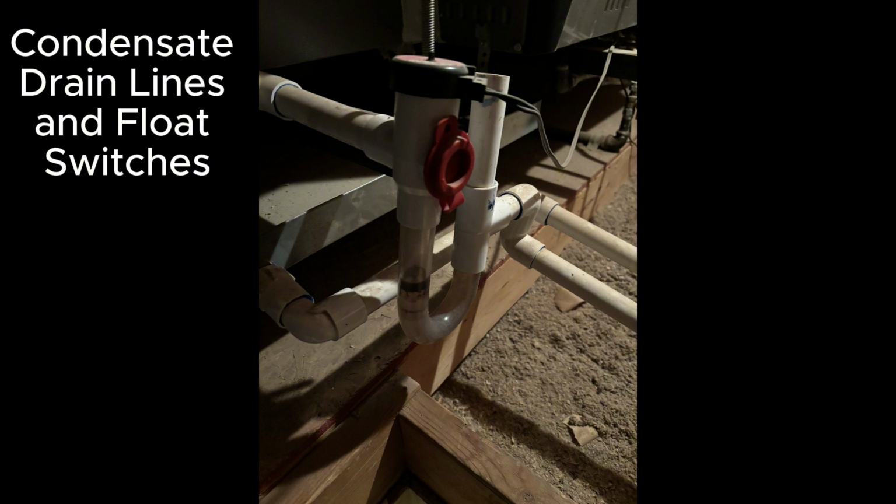So it's really good to have a float switch and a P-trap on your condensate drain line, so you don't suffer water damage, because if the float switch does not turn off the unit, more water will form, and then it will just overflow out of the drain pan in your attic or wherever the indoor section of your unit is.